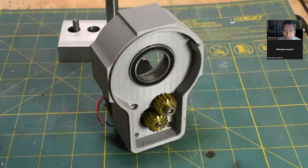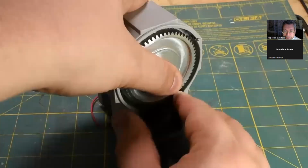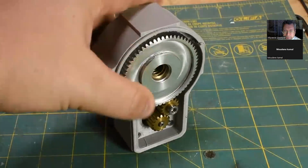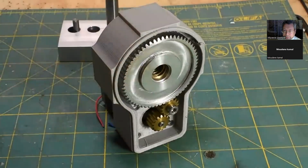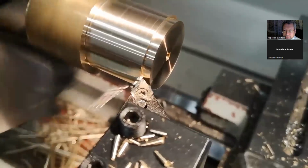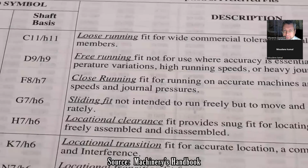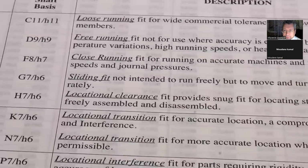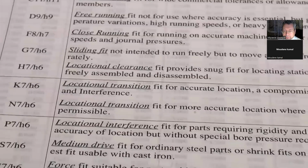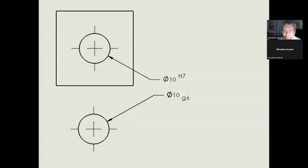If we're lucky enough to be designing both parts, we do have some discretion, but you would normally base your fit on whatever side of the fit is harder to change. The preference tends to be designing for a hole basis fit, as in general, there tend to be more options for precisely reducing the diameter of a shaft than precisely expanding a hole. So what does a fit look like in the ISO system? It's simply the two tolerance zones specified next to each other. An H7G6 fit means, for example, the hole has an H7 tolerance and the shaft has a G6 tolerance.